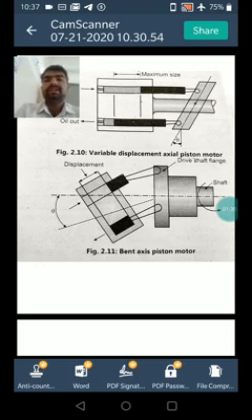swash plate reaction. Axial piston motors with bent axis design are similar to the bent axis piston pump as shown in the first unit. The arrangement between the output shaft and the cylinder block is maintained by a universal joint. Okay, the change of direction of rotation of the cylinder block and the output shaft is possible by change of direction of flow of oil.